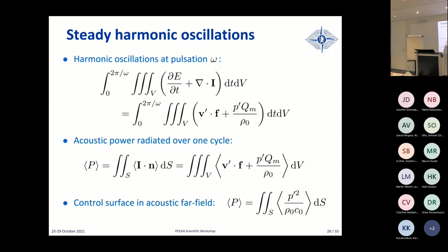So you must see the first resonant mode of the pipe as a kind of spring that you compress in each bend. When you have a maximum of pressure in here, because the tube has ingested air from both sides, and it ingests air from both sides until a certain point where you have a maximum compression inside of the pipe, and then the spring bounces back, and the pipe is breathing air out of the pipe through both directions. So by this argument, you will say that if I place my monopole at the location where the pressure is maximum, I should have maximum effect.